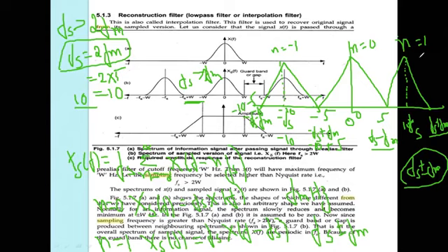Here we are using a practical low pass filter. Using the practical low pass filter, high frequencies will come inside. So to recover the original signal after the sampling, we have to use an ideal low pass filter only. See, an ideal low pass filter exactly looks like this. It removes the higher frequencies and allows only the low frequency values. And here we are not using the practical low pass filter.